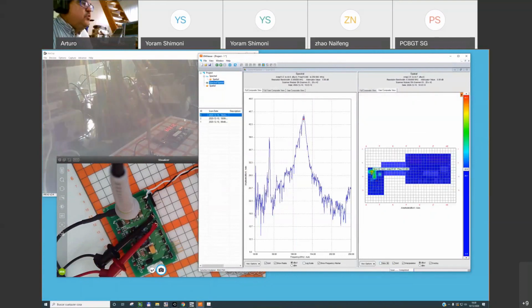This is the origin. So you can go to the circuit, you can review the layout, you can introduce some kind of snubber, or you can introduce some kind of ferrite to kill this ringing, so the emissions are solved. Perhaps you will have leakage in your enclosure, perhaps you will not have ferrites in your cables, but because you are killing this noise, the system will be very quiet. This must be done at the PCB level.